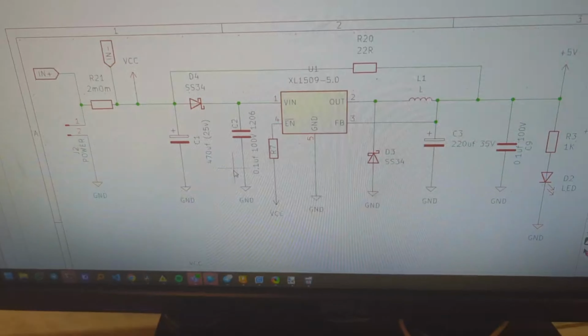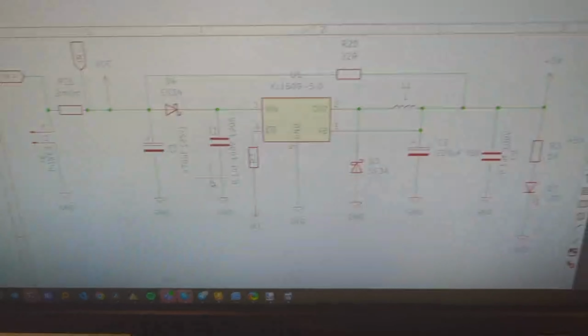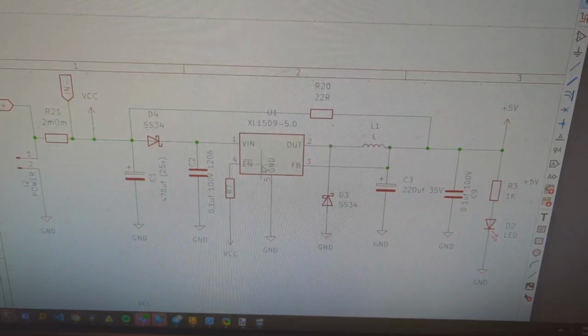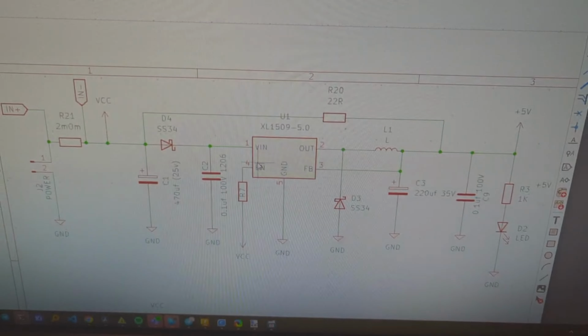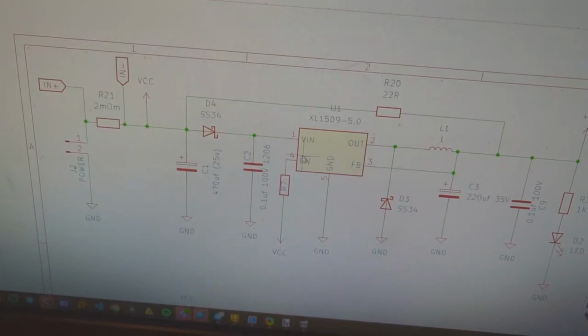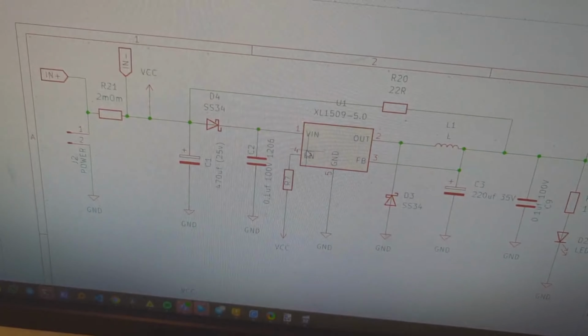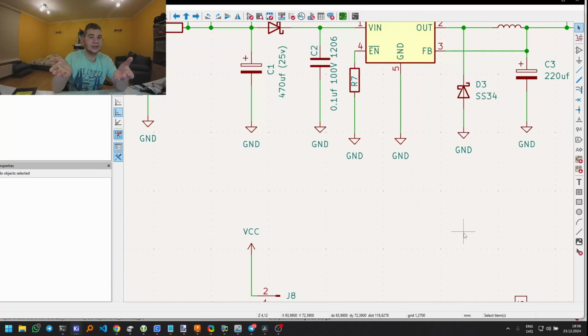And even the schematic shows you that you're doing something wrong. You see this bar, it says inverted pin. Why, and one more time, why connect it to the power? Number counter +1. Thank God, the fix is very easy. In a new revision, I've just connected it to the ground, but in the revision I have now, I just didn't install R7 and everything was working fine.